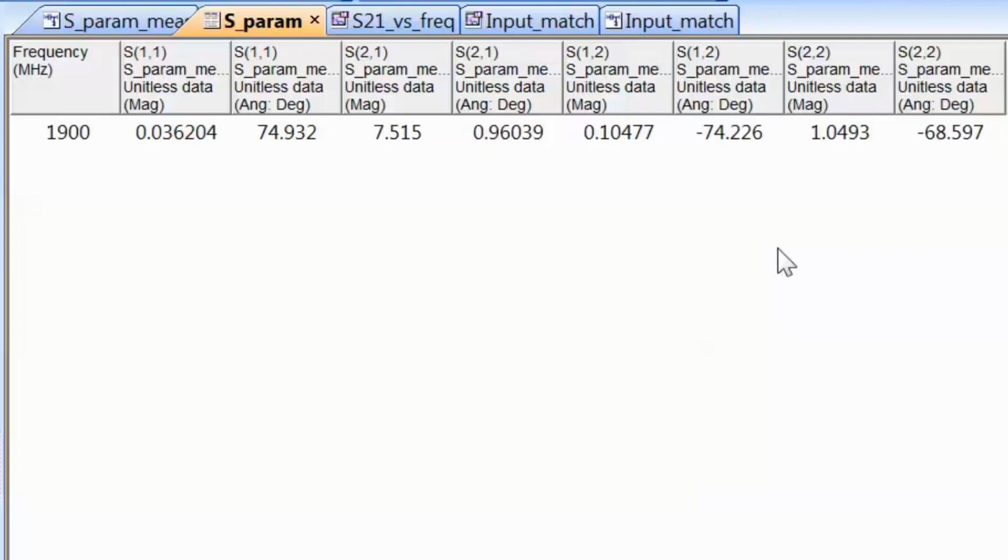So we need to make sure that whatever terminations we put at our input, they don't actually make our output reflection coefficient go over 1 in absolute value. And equally, we don't want to put terminations at the output which make the reflection coefficient at the input be greater than 1. And we will be seeing shortly how we can select the right terminations by using stability circles, which give us an indication of what terminations are safe to use and what terminations can potentially cause oscillations.